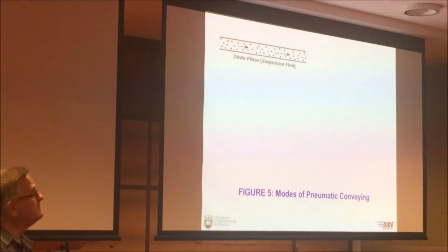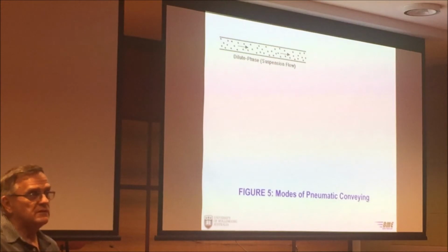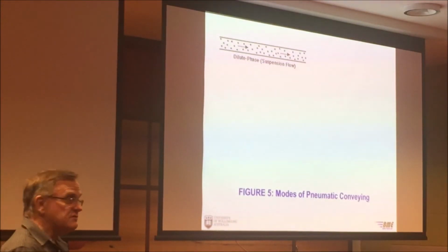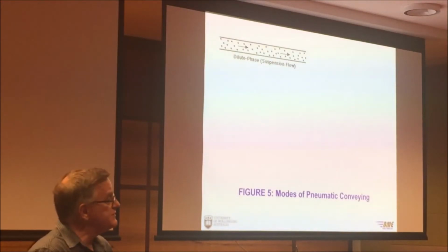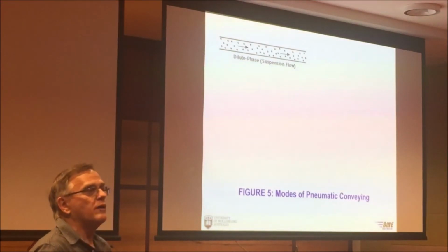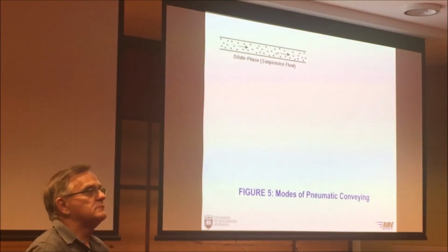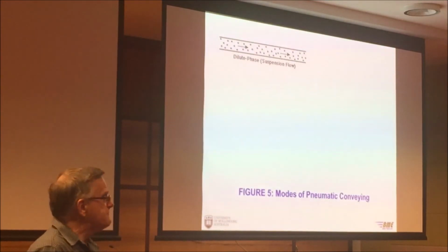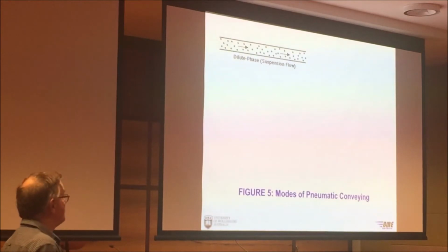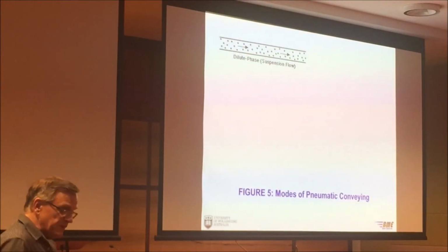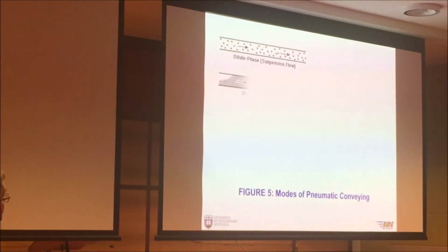Relatively easy to design. Most of your pressure loss is due to air. So you predict your air pressure loss. You can maybe even add on a percentage to allow for your particle losses. But once you get the higher and higher tonnages, the situation changes, and your product becomes more a dominating factor. Anyway, so that's suspension flow or dilute phase flow.